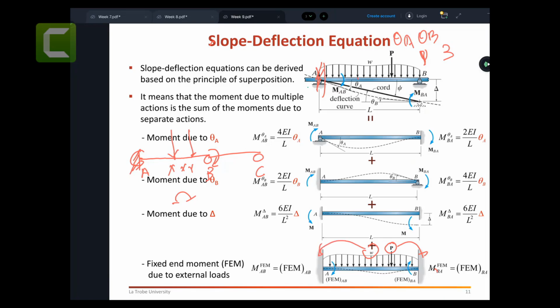So the first job: we clamp it, we arrest all the joints to make them fixed, to make it a kinematically determinate structure, to make the kinematic indeterminacy equal to 0. Everyone understand that? We go there, bang, we put the nail, we put the hammer, and then we say this joint doesn't rotate, doesn't displace. We fix it with plates, weld it, or clamp it. That is job number 1: make the kinematic indeterminacy 0.